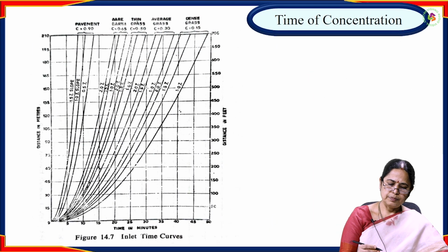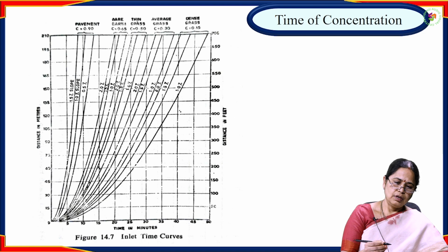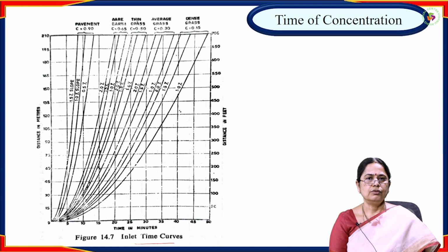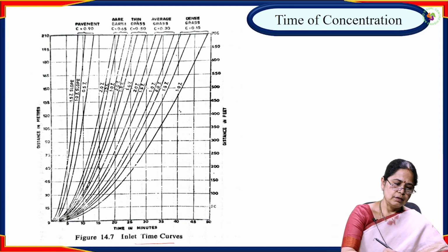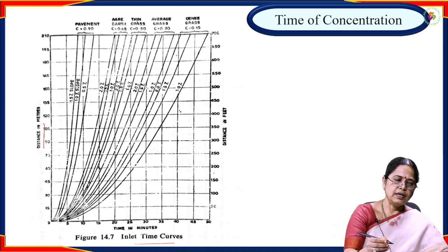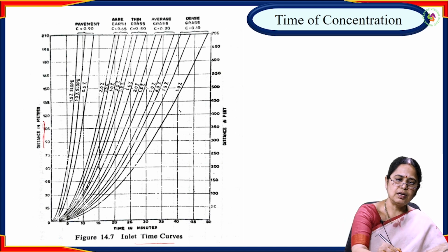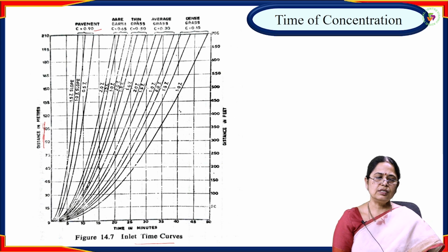So here this picture is used to calculate the inlet time of that particular storm water. These curves cover the distance in meters, and the smoothness of the pavement.